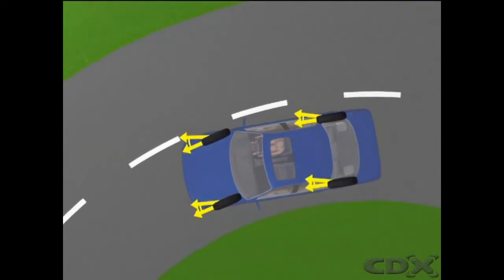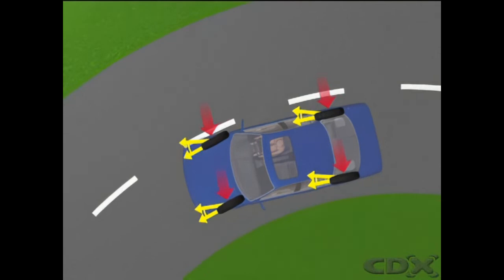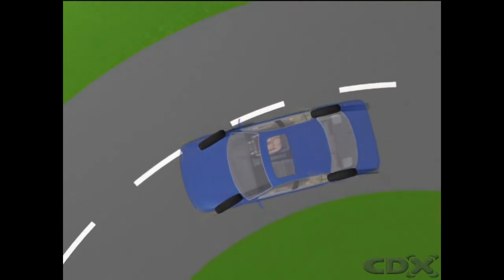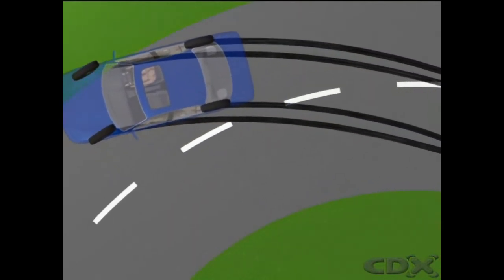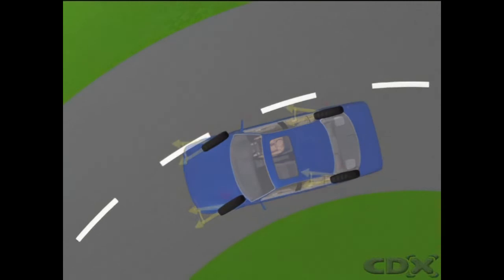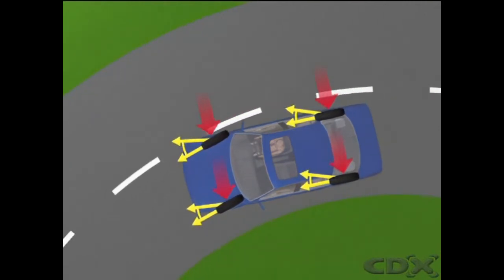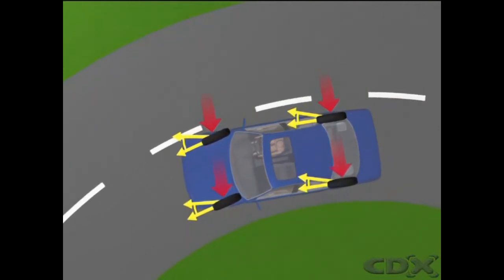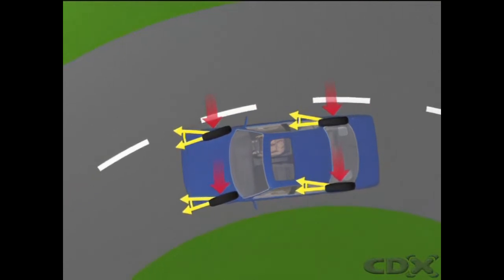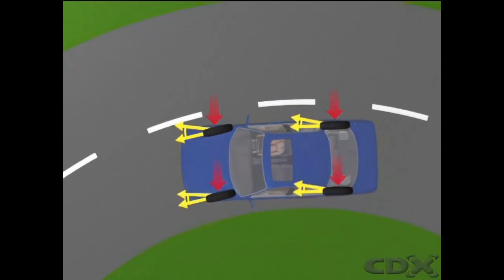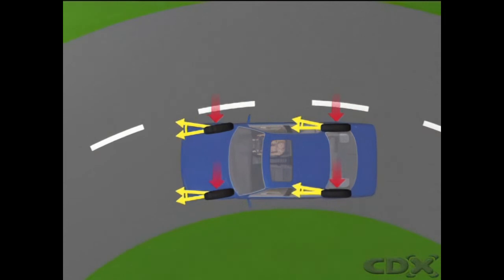Both slip angle and cornering force increase until a point is reached where the tyre slides and the only resistance comes from sliding friction across the road surface. The tyre grips again only when the vehicle has slowed or is making a turn with a larger radius. That is, when the side force is reduced to a level the tyre can withstand without skidding.